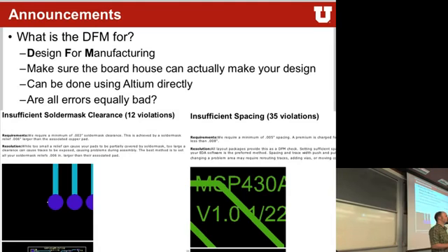You might have asked what these DFMs are all about, like the free DFM service that we use. DFM stands for Design for Manufacturing. So this is basically a test and a check of your PCBs telling you if this board can really be manufactured. What you saw is sometimes you had errors that were a little bit bogus and they fixed them themselves, so they were not showstoppers. Other times they told you these are actual showstoppers, which means that something is really odd or strange with your PCB design, something that they don't feel confident about that they can actually manufacture.